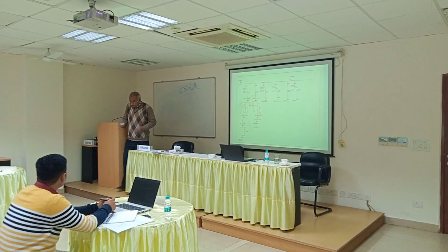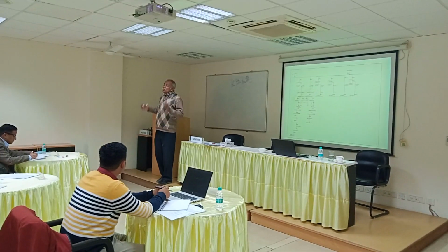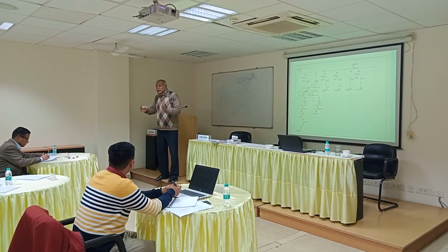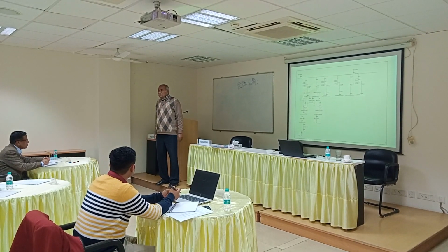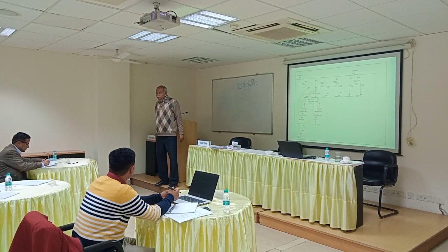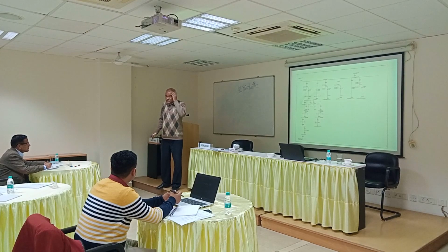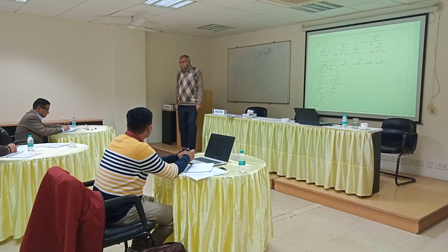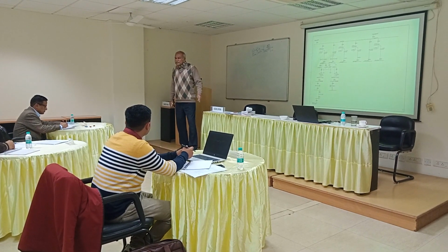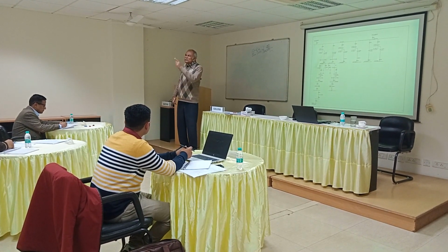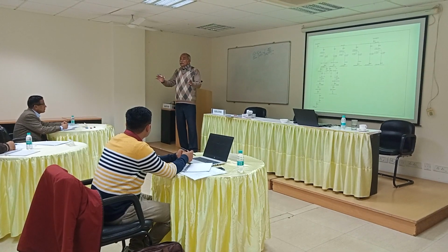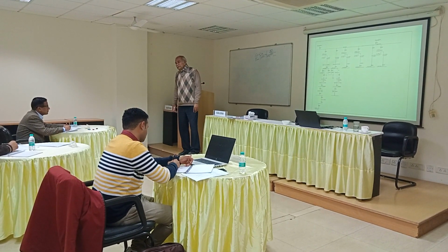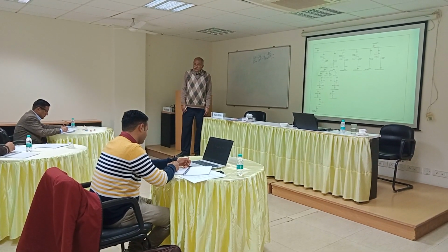What I want to say is, when you go for fault current calculations, these are the minimum information you should have. Now, cable impedance, from where will you get it? You know the size of the cable. You know the length of the cable. So the cable manufacturer's manual will tell you how much the impedance is. So, from there, you get it.